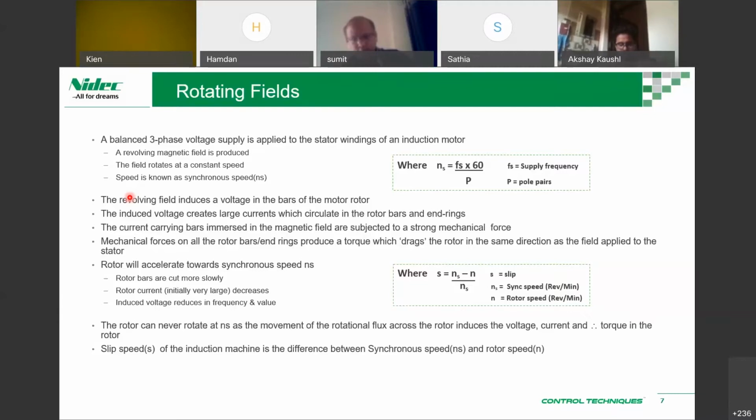Okay, if you were to calculate the percentage, it is 1500 synchronous speed minus rated rotor speed, which is 1450, divided by synchronous speed 1500. So you have 50 divided by 1500, you get about 3.3% slip. So that's basically roughly the slip calculation.